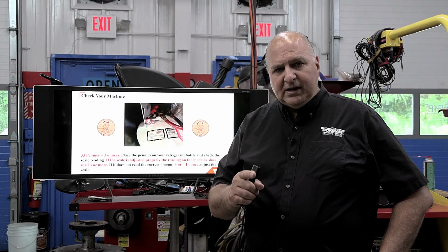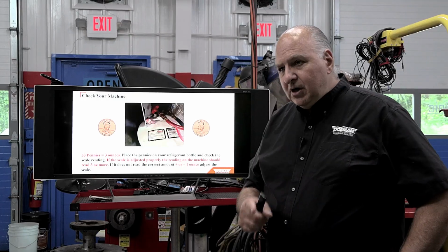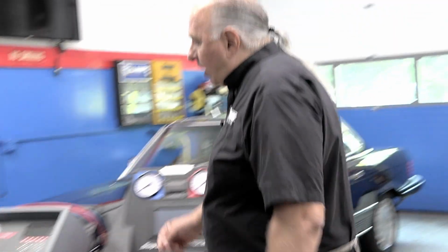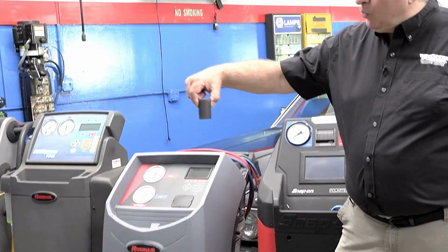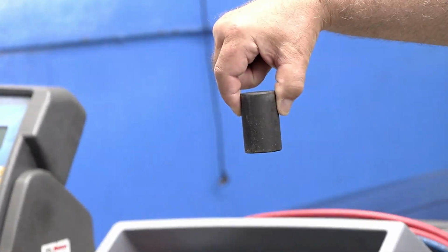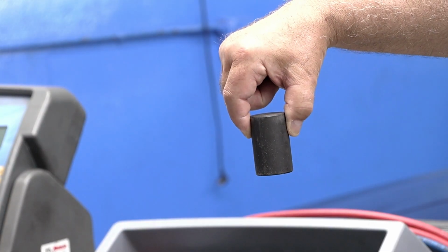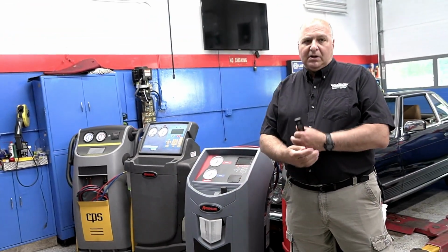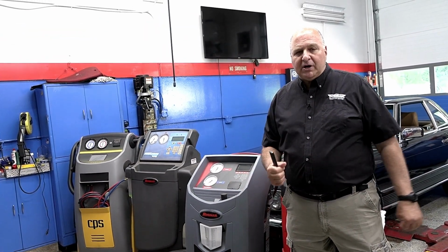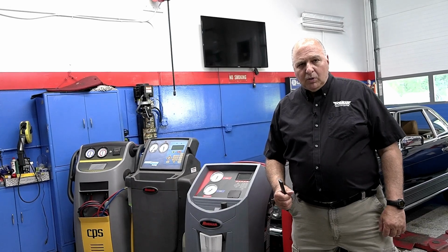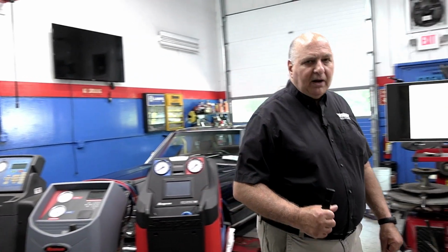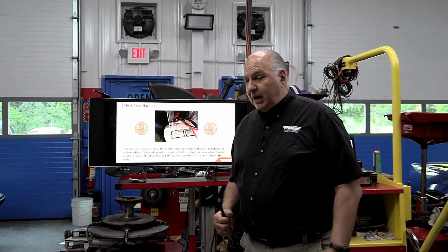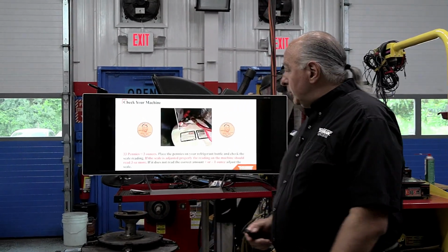You got 33 pennies? I'm serious, 33 pennies? Because I can tell you, you probably lost your weight. Here on this Robinair machine, this is the weight. It goes on the bottom of the machine, and you've got to make sure it calibrates correctly. In fact, this machine, when it was brand new, wouldn't calibrate correctly. It would put too much refrigerant into the system. The service guy came out from Robinair. He had to take it in because there was a defect in the scale. And the thing was only, I think, a week old when we tried it.